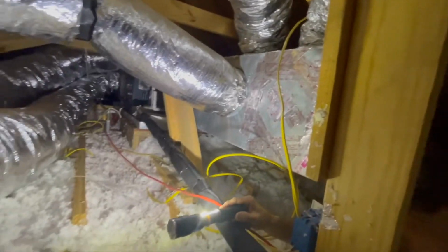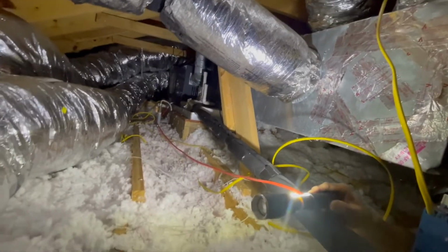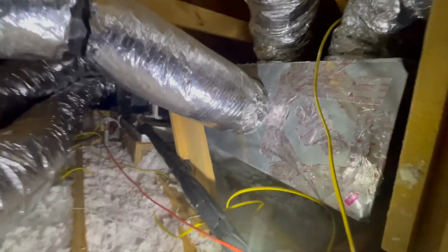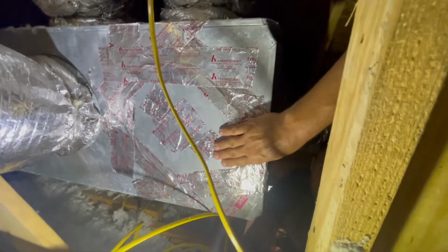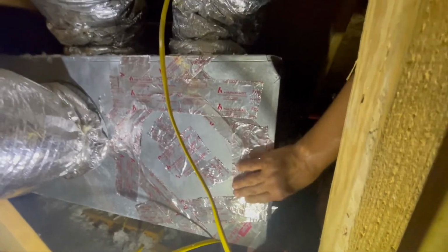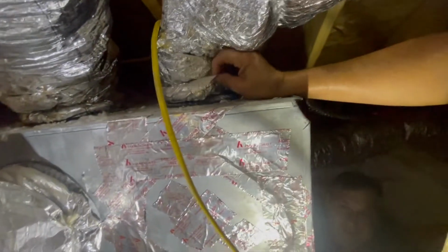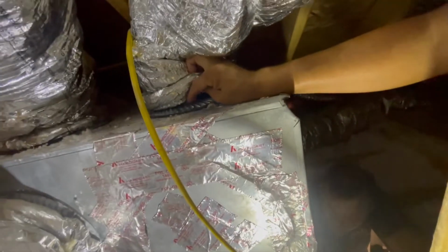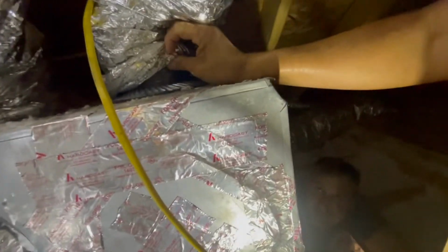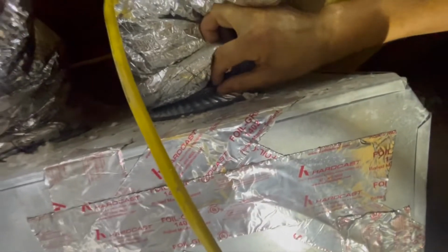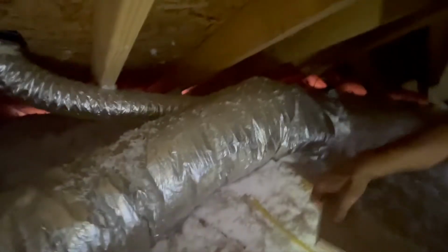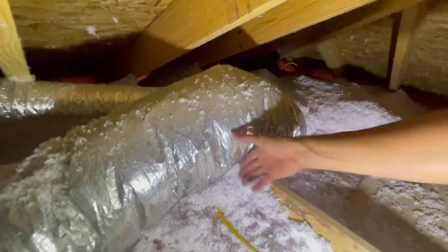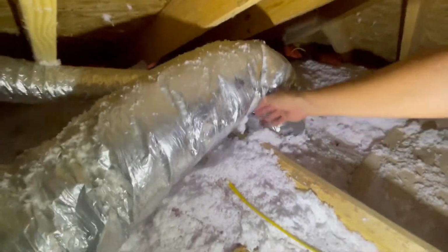Okay, so we're up here, and as I suspected, they didn't necessarily follow the best installation practices. It's pretty tight. We don't have any type of serviceable access, but as you see here, it looks like some mistakes were made, and so they taped all that back on. We've got some sticky collars designed for duct board, but there's no sealant on our ducts, which are also pretty damp. Lots of compression in the duct system too, which is going to result in a lack of performance.